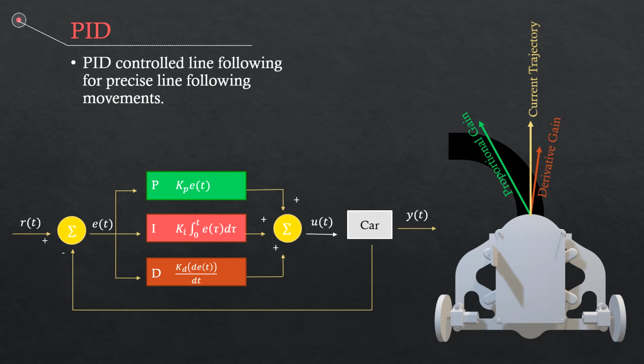Finally, with active mechanical components, any mechanical defects could lead to a steady state error. In line following, the integral term Ki accounts for this by monitoring the error history and adjusting to return to the center of the line. The PID gains were tuned using a combination of the Ziegler-Nichols method and empirical tuning methods.